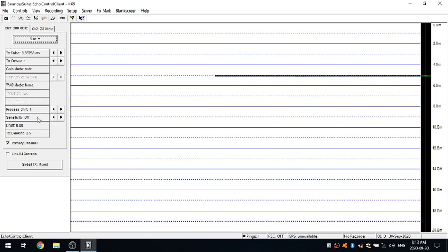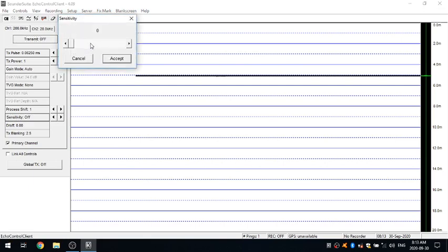The sensitivity control. Where this comes into play is if you get into an area where you can see on your echogram a very dark bottom and you can see a slight gray layer on top of it, a very, very light layer. Typically, even with a 200 kilohertz signal, you might be transmitting down through and digitizing on the harder bottom. If your application is that you want to actually digitize along the top of that very, very soft fluff layer, let's say, you can increase your sensitivity.